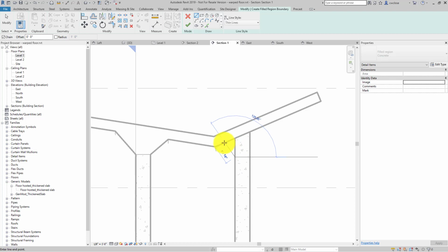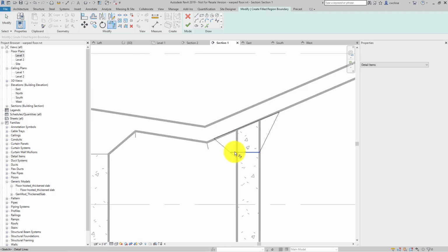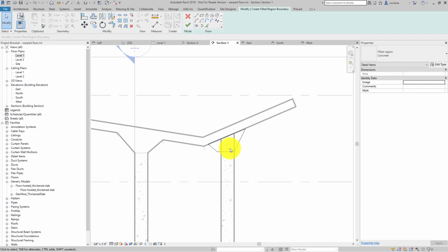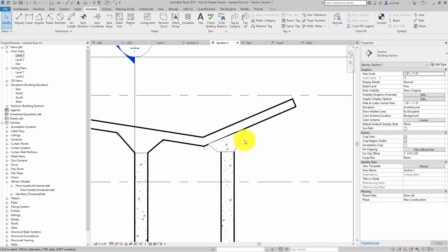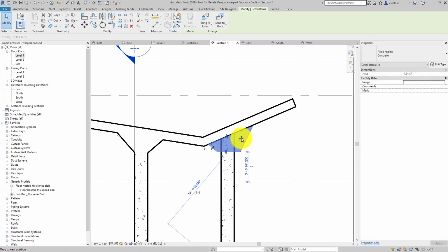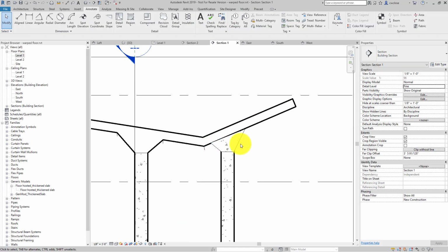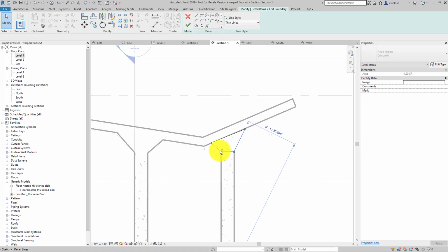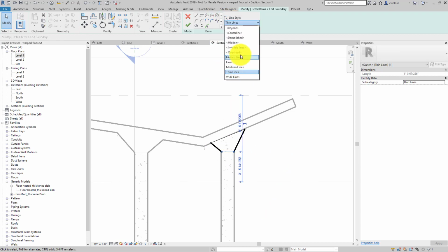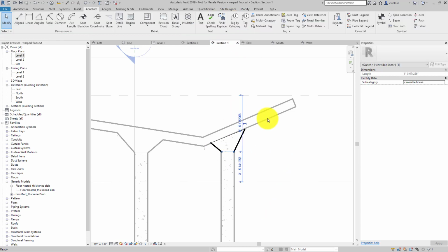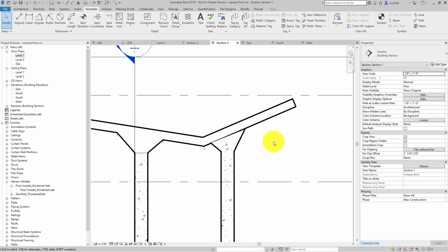and draw essentially the same thing as a filled region. And again, maybe this goes flat across like that, whatever it is. Or maybe it runs perpendicular, I don't know. But the point is there's your concrete filled region. Fix it as you need to have the line work right. Again, that could be maybe a better approach. Obviously, the line work probably needs to punch a little bit here. You could go ahead and do wide lines there. You could make this an invisible line, so on and so forth. Again, just trying to get you a better picture of how this works.